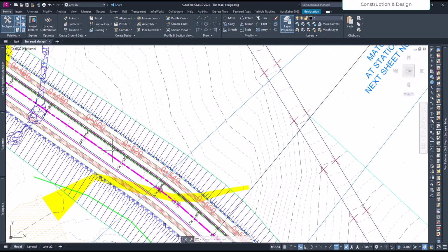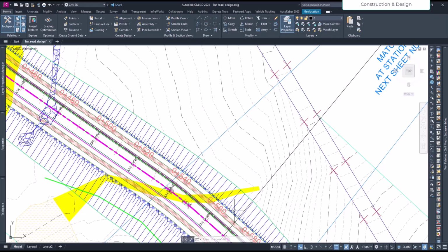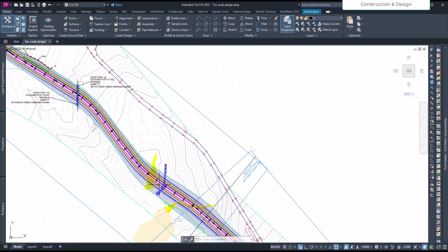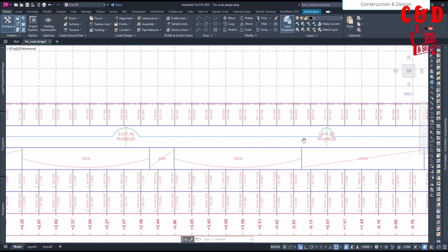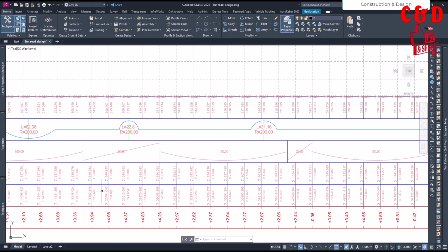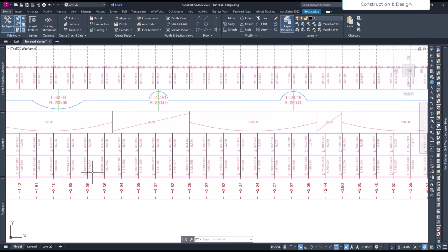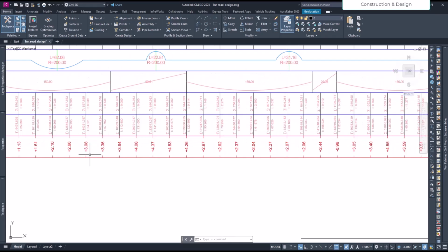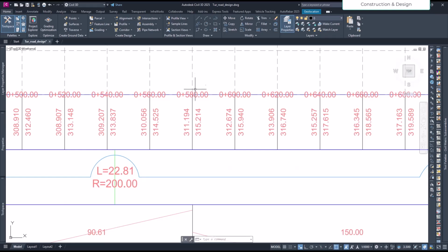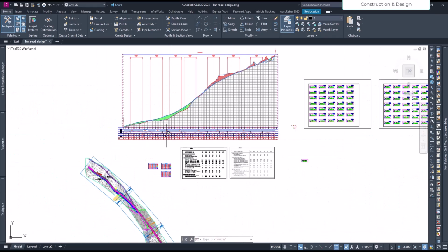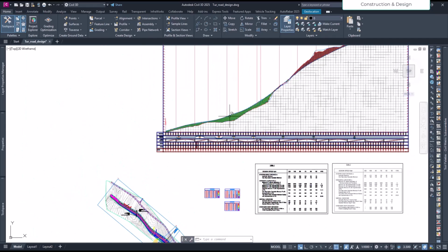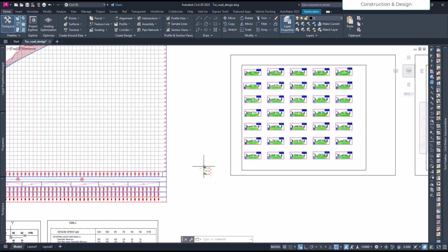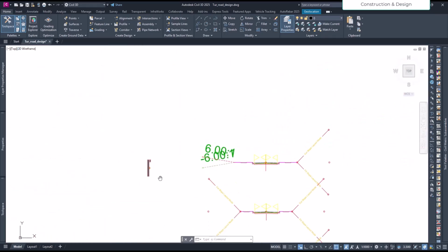Let's say somewhere here, 500 to maybe 580, 600. I think it appears to be a perfect location. Let's verify from here, 500 to 600 something. So 500 here is 3 meters. You see from here 460 is 3 meters plus. So from 460 till this location, 580, we add the barrier. We will use the same alignment and same profile, but we need a different assembly. So let's do it.